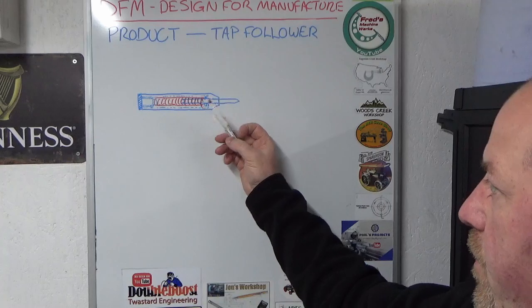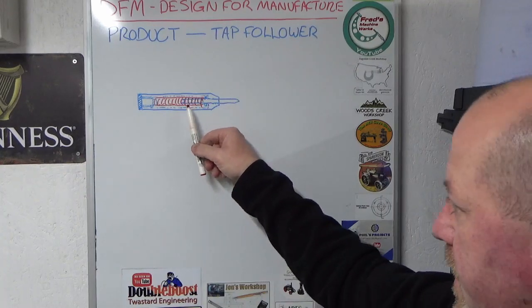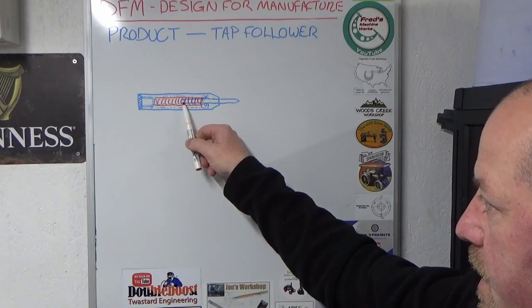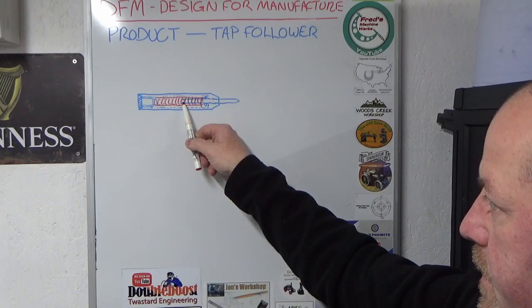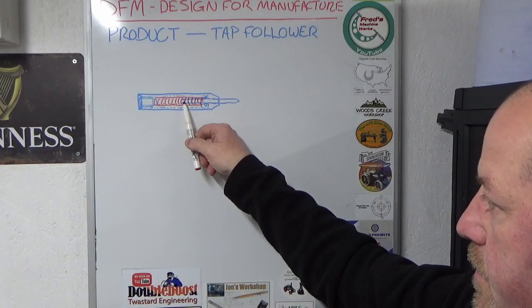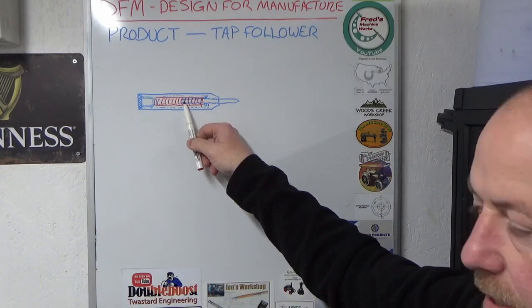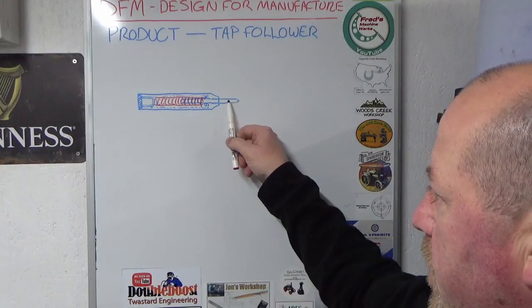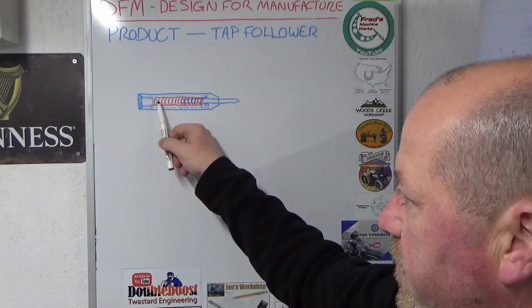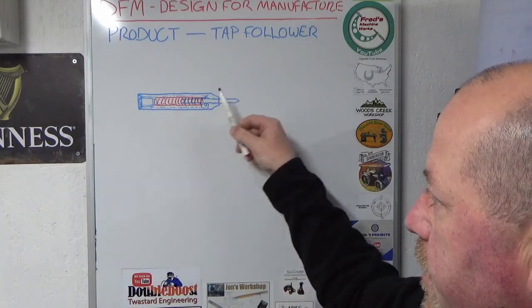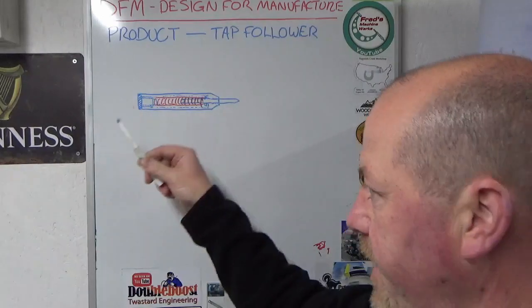And what I've tried to draw there as well, just very roughly, is because this is a double-ended pin with two uses, the back half of the pin only needs to take up about 50% of the length of the spring, whatever the length of the spring is, so that when you compress the whole thing, there's room for this to move back up before it bottoms out on the plug at the back. All of those dimensions are yet to be figured out.